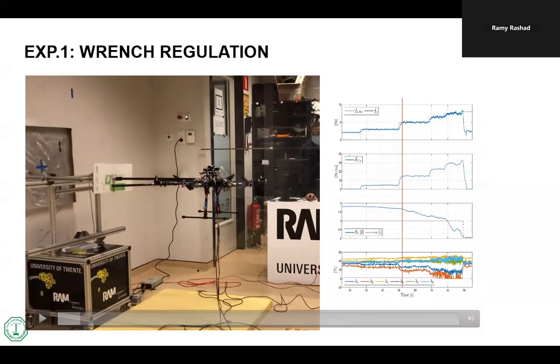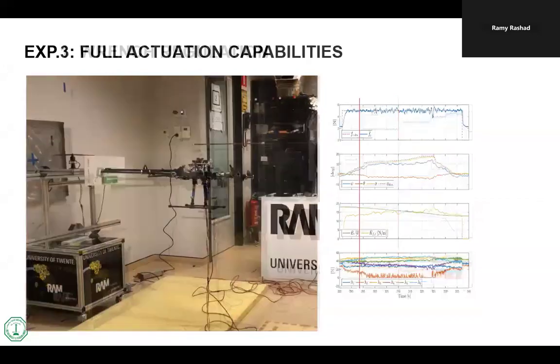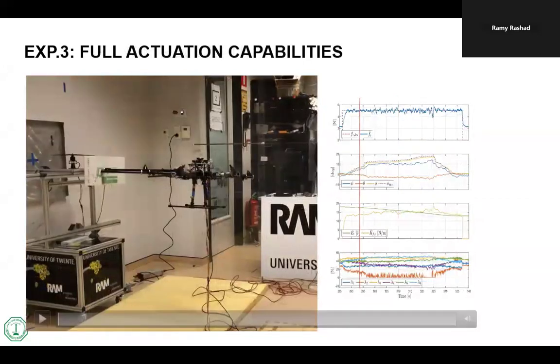When we do the modulation of the spring, it's not just about the interaction. It's just because we have a variable spring now. This is what loses passivity. The system now is supplying some sort of energy, because of the changing of the stiffness. It's power.